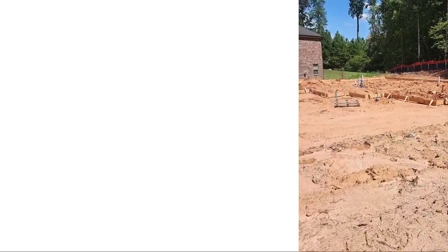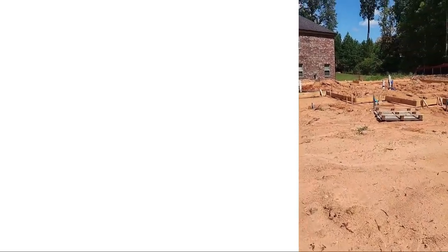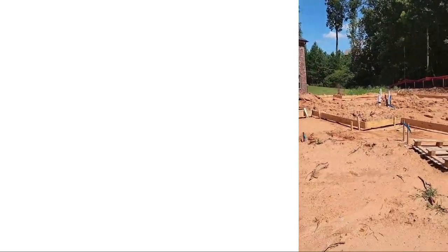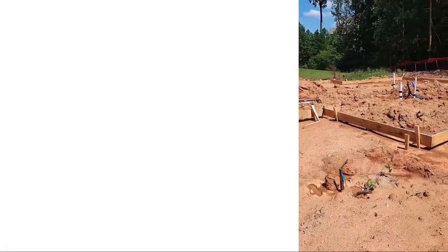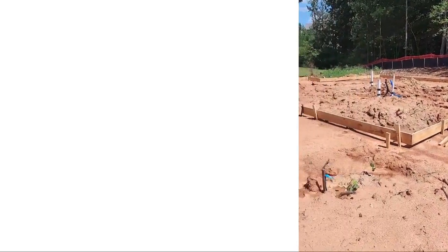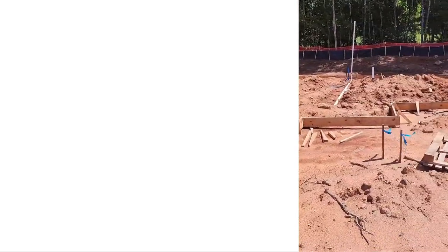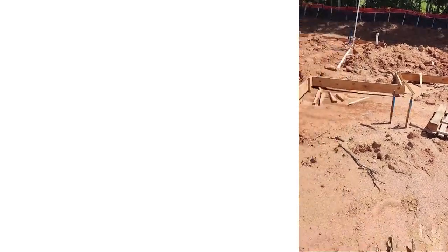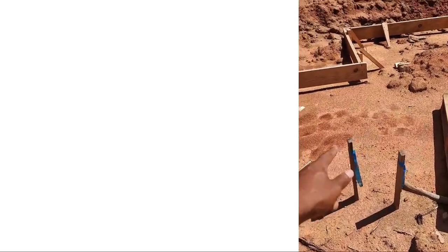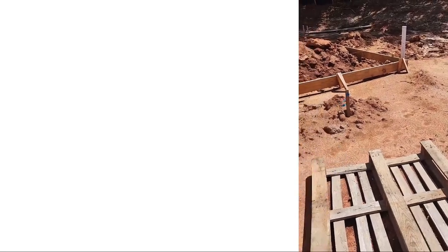Those are the stakes put on by the survey company. When we finish clearing the lot, they come out, and they're going to actually, because how do we know where we're going to build? You recall in the previous video, or even in our live, I told you, we have people that built the houses the wrong way, the wrong orientation. So we called the survey company to come out. And what they're going to do is they're going to put stakes out. They'll put a stake like this and a stake like this. These are our house corners. A stake like this and a stake like this.